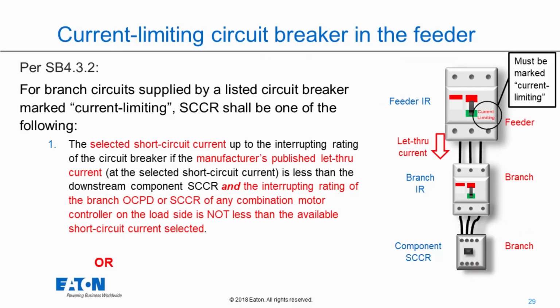Next, we're allowed to use, so we were allowed to use a power transformer. We're also allowed to use a current limiting circuit breaker in this feeder. And something that is really weird and quirky but important to know about current limiting circuit breakers is that a current limiting circuit breaker does not count as current limiting unless it is marked current limiting. Every circuit breaker technically is a little bit current limiting, but unless it is marked current limiting, we don't get to use this step. So first and foremost, marked as current limiting.